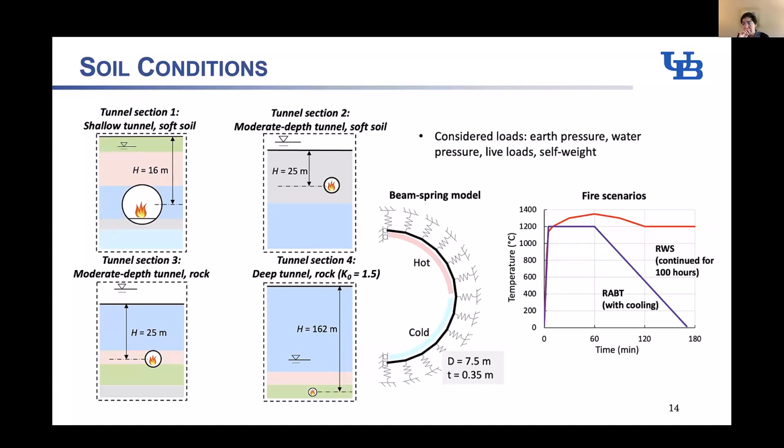One thing I want to quickly mention, considering the time, I'm not going to go into details, but this time at ambient temperature, we wanted to verify the spring models here and the geotechnical consideration. So when we designed these 4 tunnels, we modeled them in SAFIR. We analyzed them using elastic equations that are available out there.